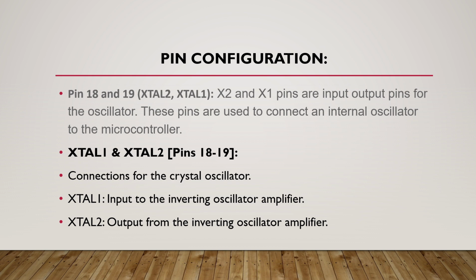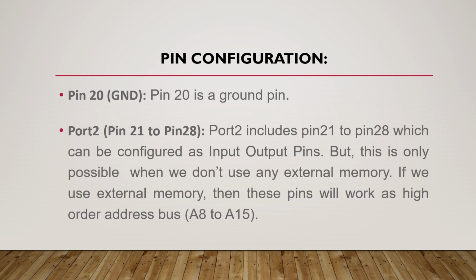So this type of high input data and low input data is used by the 8051 microcontroller, and these two pins, 18 and 19, are used for the oscillator. Okay, next, the 20th pin. The 20th pin is a ground pin.